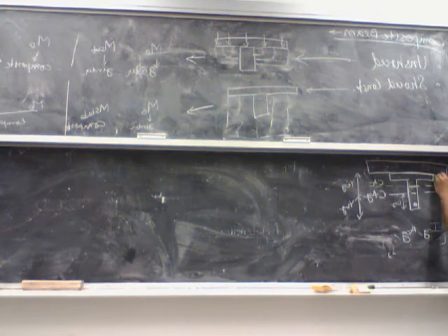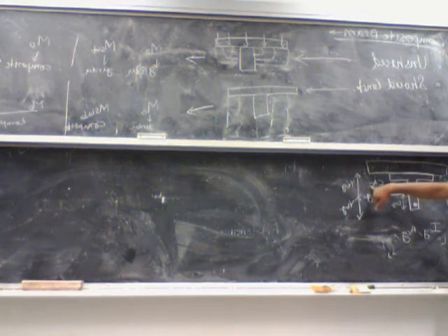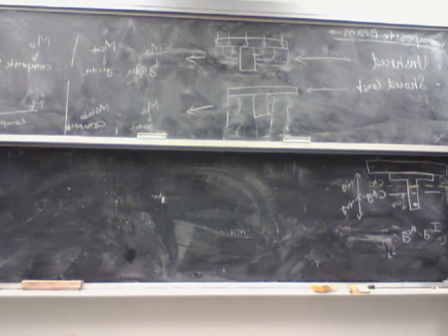One extra term that we define is Y prime TC, where Y prime TC is the distance to the top of the girder from the centroid of the composite section. So Y prime TC is simply YTC minus the depth of the slab.